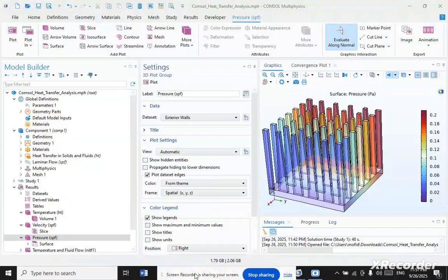To address the issue of high heat flux dissipation, several strategies, including spray cooling, microheat pipes, jet impingement, and etc., have recently been developed. Based on these techniques, fluid flow through a microchannel heatsink has gained worldwide attention due to favorable characteristics such as high surface to volume ratio, lesser material cost, low coolant requirement, quick response time, and etc.